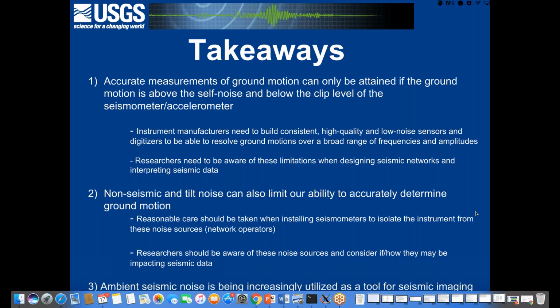And it almost seems like the sensor becomes more sensitive to magnetic fields within the casing. I don't think we exactly understand why that is, if the magnetic flux lines are maybe focused in the casing. But it seems like some of these stainless steel casings could actually enhance a sensor's sensitivity to magnetic fields. But that, again, is an active area of research, I'd say.